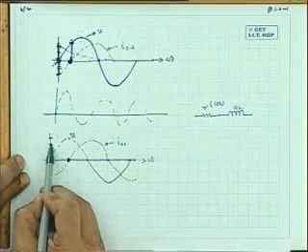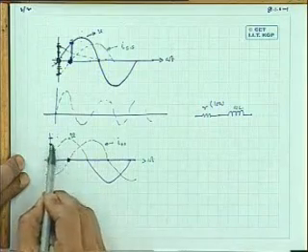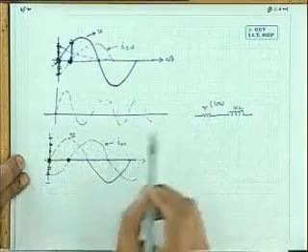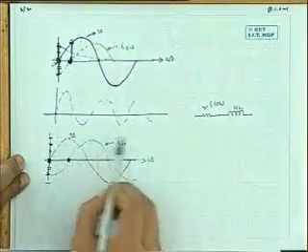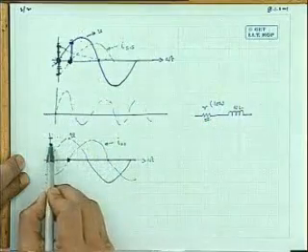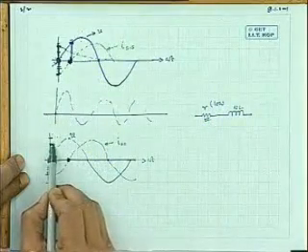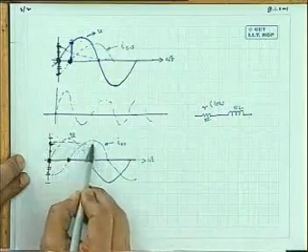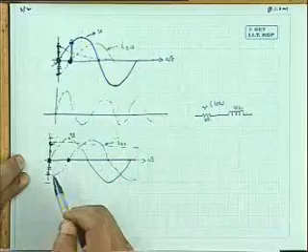And this current, there is no voltage to support this current. This current will decay with the time constant of the circuit, L by R. Now, here in this circuit, I have assumed R to be very low. So, this current will fall rather slowly here, like this.